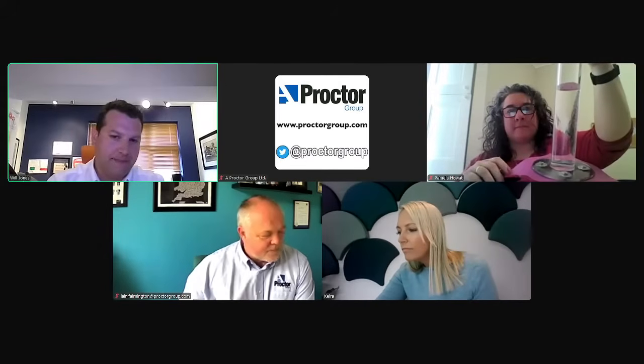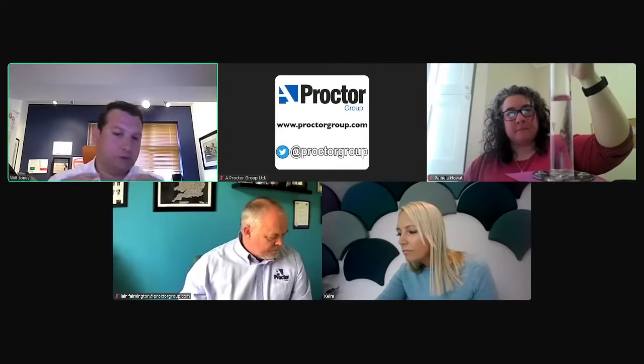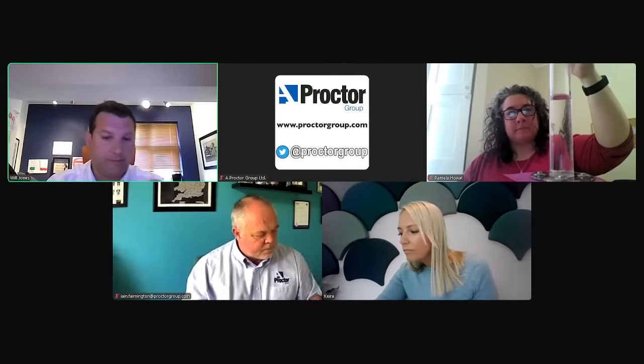You'd see this at trade shows quite often, and when our guys are doing CPDs, they tend to take one with them as well. It's basically, as you can see, an acrylic tube. It's split into two chambers. The top chamber is separated from the bottom chamber with a membrane, in this instance Proctor Air. The top chamber is filled with water, which sits on top of that membrane, and the bottom chamber has got a little pump where you can pump air into that bottom chamber, and you can see air bubbles coming through the membrane. So what that's a really good demonstration of is how air permeable a product like Proctor Air is, but it's not allowing the water to pass down into that bottom chamber. So in this instance, keeping the roof watertight.